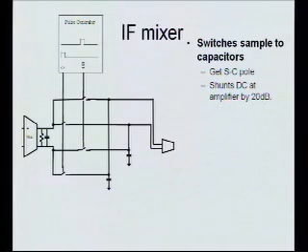And in fact, any sort of sampling ADC will have the same problem. It'll mix down all the harmonics. So you would have to include a lot of anti-aliasing filter to go straight to an ADC, or I'll sample at a very high frequency. So how do I get around that here?